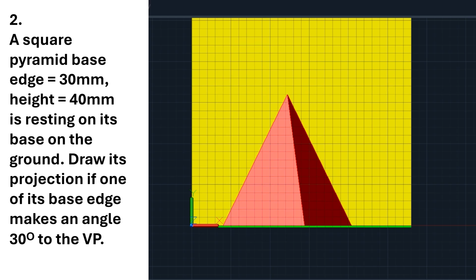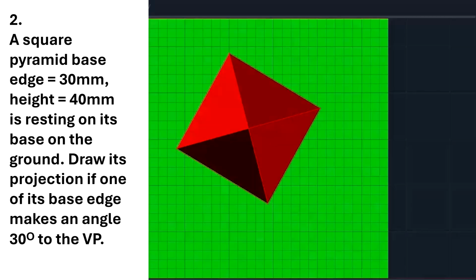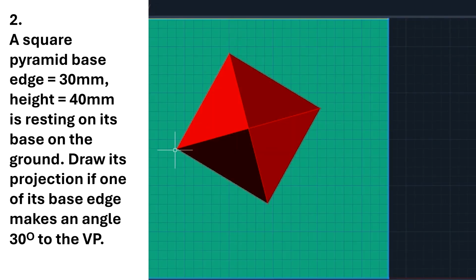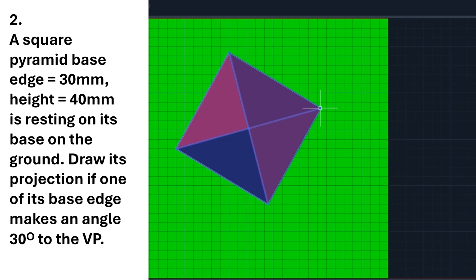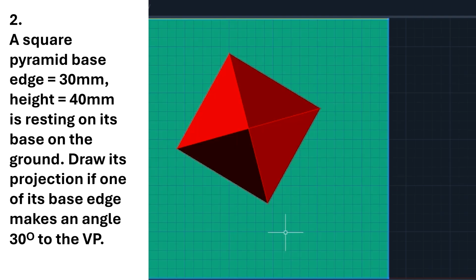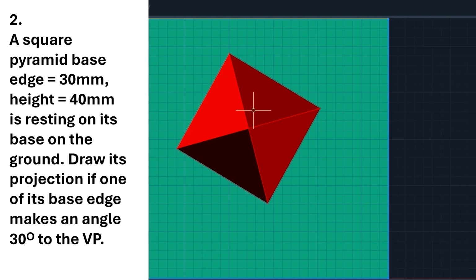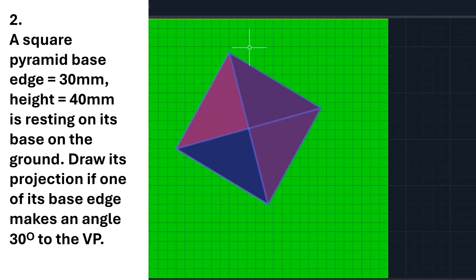If you go to the top view, observe the leftmost corner and rightmost corner, and draw a line joining these two. Because we are seeing the front view, everything on this side will be visible. The portion behind this line will not be visible. That means the edge A to O will not be visible in the front view, so you represent it with a dotted line. That is how we draw the projections.